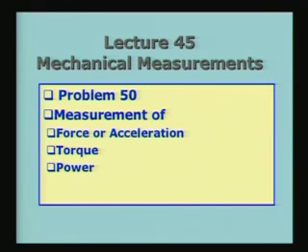In this lecture, problem 50 is the one which is going to come from the previous lecture, whatever is left out. Then we will look at some interesting things about measurement of force or acceleration, torque and power. The measurement of force and acceleration, torque and power are very important from the point of view of mechanical engineering applications. For example, if you have an engine or a power producing device, we would like to measure the power output, and the power output requires the measurement of a torque and the speed of the engine or the machine.